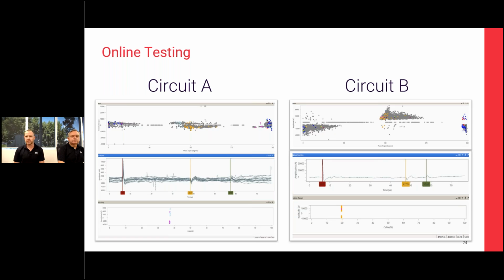The first test that we ran was a cable data collector test, where we put high frequency current transformers around the sheaths of the cables at the ends and run an online test. We get our computer, our cable data collector, run some software, and run a capture on all the phases. We do this without turning the cable off, so there's no shutdown. We do it while it's in service.